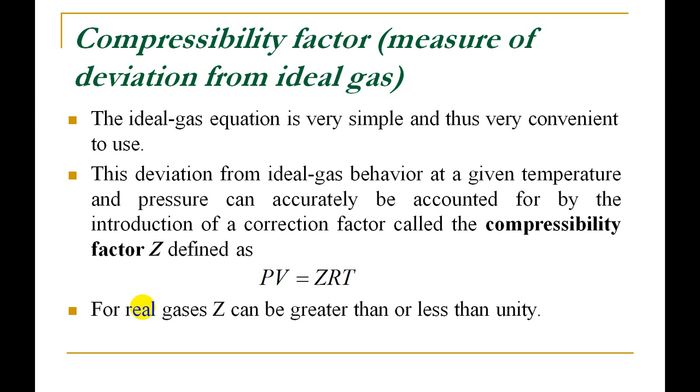Again, we have pressure and temperature. So first we determine the state, because to use the table, first we have to determine the state. Then after we determine the state, we can read the volume from the table, or we calculate it. So it's a little bit long steps compared with the ideal gas. So we try to assume other substances as ideal gases, which means we have PV is equal to